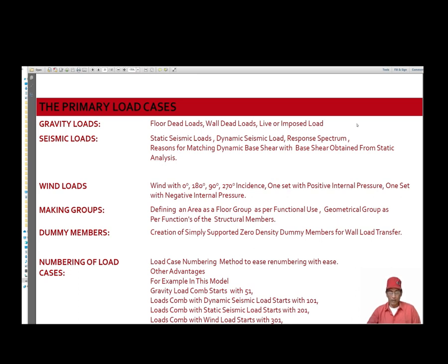So the time period calculated by the software is as per the stiffness of the bare frame. But in static analysis, the time period is calculated based on the empirical formula derived from various experiments and seismic records obtained from actual buildings. So actual buildings are not a bare frame. They consist of walls, various types of fittings, etc., which actually increase the stiffness of the building. So these non-structural materials do not know that they are not structural. So obviously, whenever there is a seismic occurrence, they also take part in resisting load with structural members.